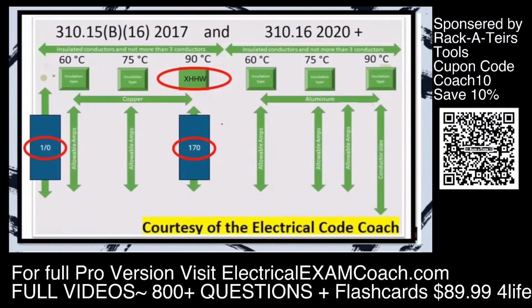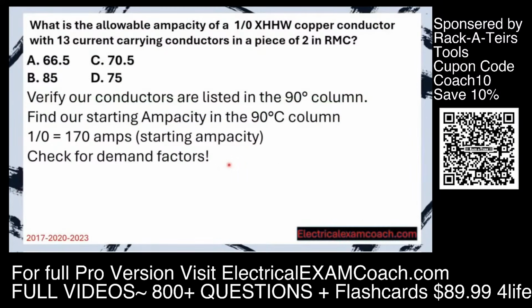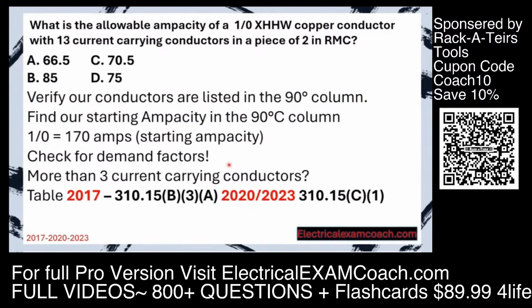We head to our primary ampacity table. We're on the copper side. We start until we find 1-aught on the left. Then we cross all the way over to the 90, and we find that it's 170 amps. Now we check for demand factors. Are there more than 3 current carrying conductors? There are. So we must apply the adjustment factors that are listed in these tables.